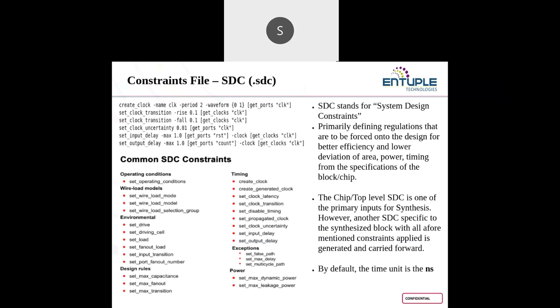Usually this is at the chip level. Usually who will be creating this SDC file? It is usually called the chip level architecture. Whatever SDC I am writing is usually called a chip level SDC, and it is also one of the primary inputs for the synthesis process.